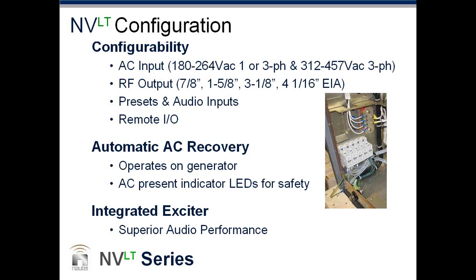Yeah. The wires that exit from that terminal block shown in the small picture there just have to be repositioned, and they're all ferruled wires, so they're very easy to remove and reinsert. And so you can go from three-phase 208 to single-phase 208 to three-phase 380 in literally 5 minutes. That's one of the tangible benefits to these sorts of supplies.